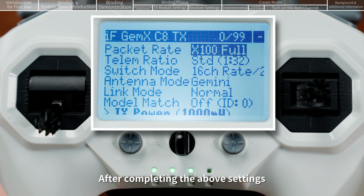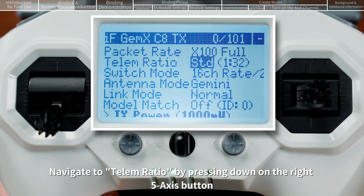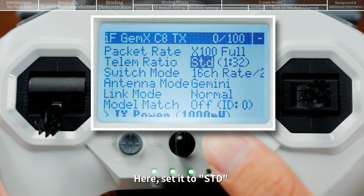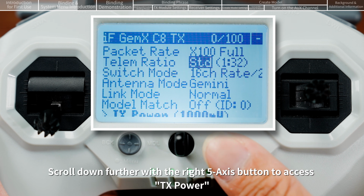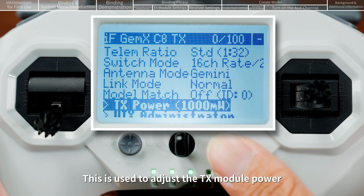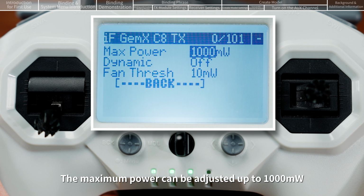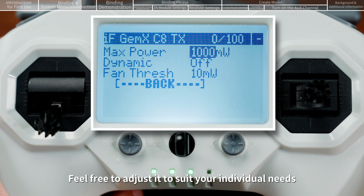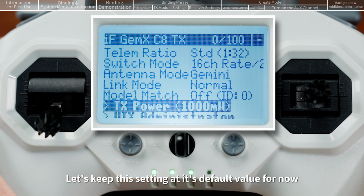After completing the above settings, navigate to Telem ratio by pressing down on the right 5-axis button. Here, set it to STD, the standard mode. Scroll down further with the right 5-axis button to access TX power. This is used to adjust the TX module power. The maximum power can be adjusted up to 1000 milliwatts. Feel free to adjust it to suit your individual needs. For daily use, setting the TX module to 100 milliwatts is sufficient. Let's keep this setting at its default value for now.